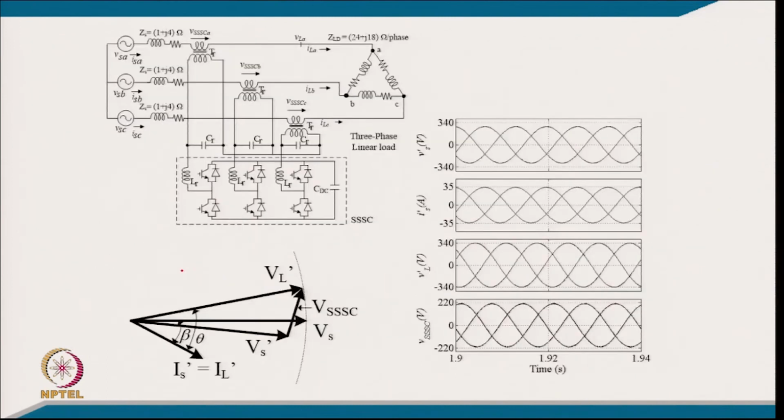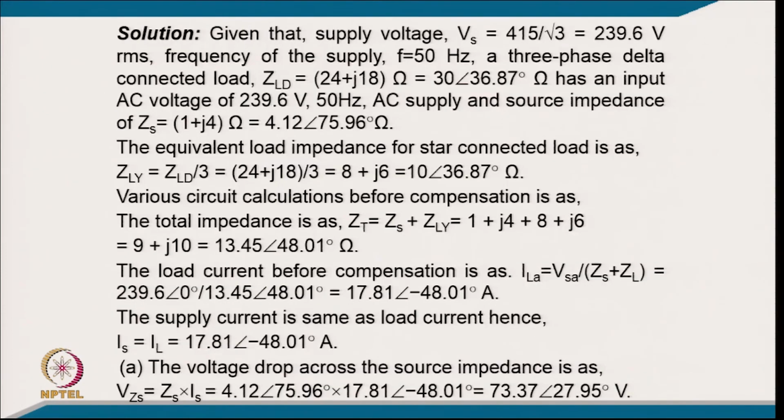This is the typical circuit. So, we have a source impedance that is inductive and the load is also a lagging power factor load. So, if the compensator is not used, certainly the voltage will drop across the load because of poor voltage regulation. So, we connect the series compensator and we inject the voltage, so that the load voltage here is the same as the source voltage, and this is the point of common coupling voltage, source current, load current, and compensated voltage, with the phasor diagram.